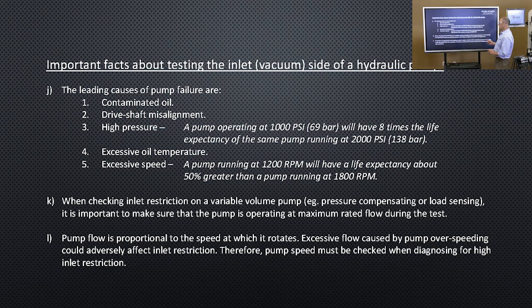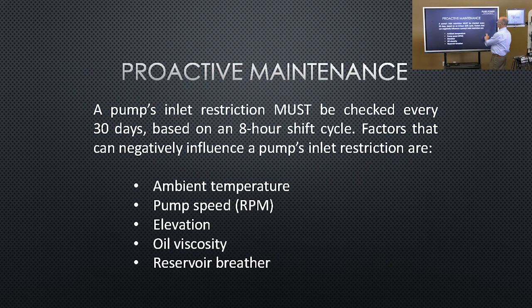Pump flow is proportional to the speed at which it rotates. Excessive flow caused by pump overspeeding could adversely affect inlet restriction. Therefore, pump speed must be checked when diagnosing for high inlet restriction. This is particularly true of variable speed drive applications.